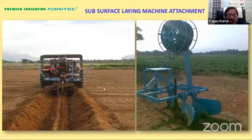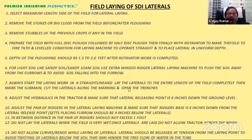So this is the tractor attachment that is there, and the drip coil will be put on the coiler, then it passes through the tube over here, and then directly at the required depth, the attachment will ensure that the drip lateral is laid at the required depth. So field preparation and land preparation, all this has to be done. It has to be a level field, and then you can go about doing the entire laying of the subsurface drip irrigation laterals. And here I would just like to elaborate in a simple way what are all the steps.